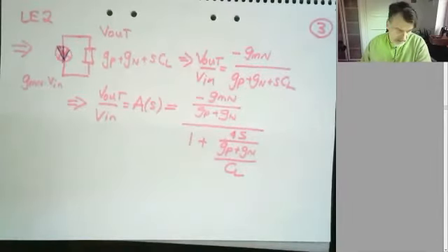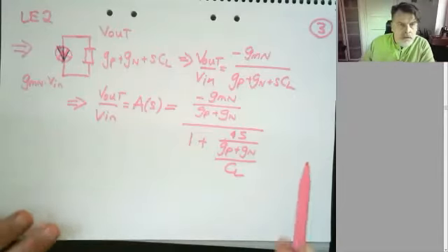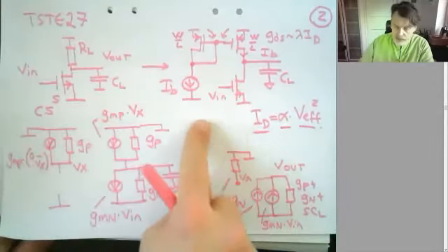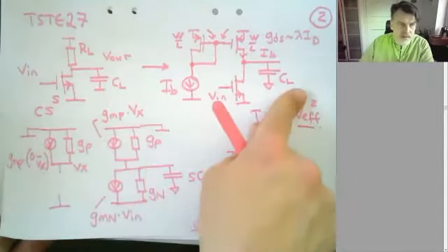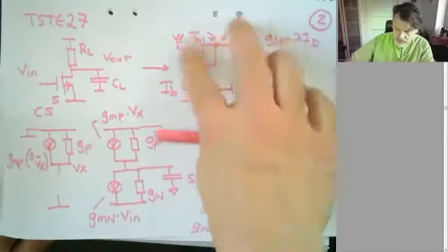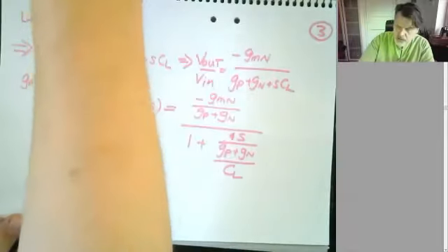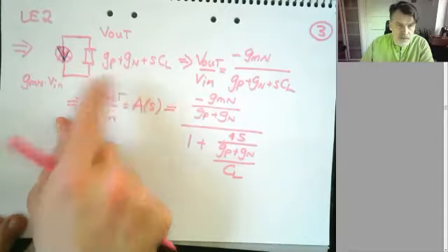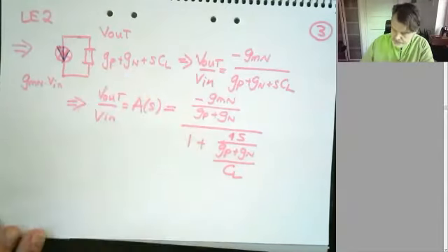So we're going back to the basics here to be prepared for what we need to do next. All right, so resistive load, big and evil. We need active load. We control the active load with the current mirror. We conclude that the current mirror does not add anything to the right-hand side. So this is sort of isolated from the actual gain circuit, which is here. We can do the small signal schematics, and we see that we get GP plus GN. Previous time we had something like RL or GL here.